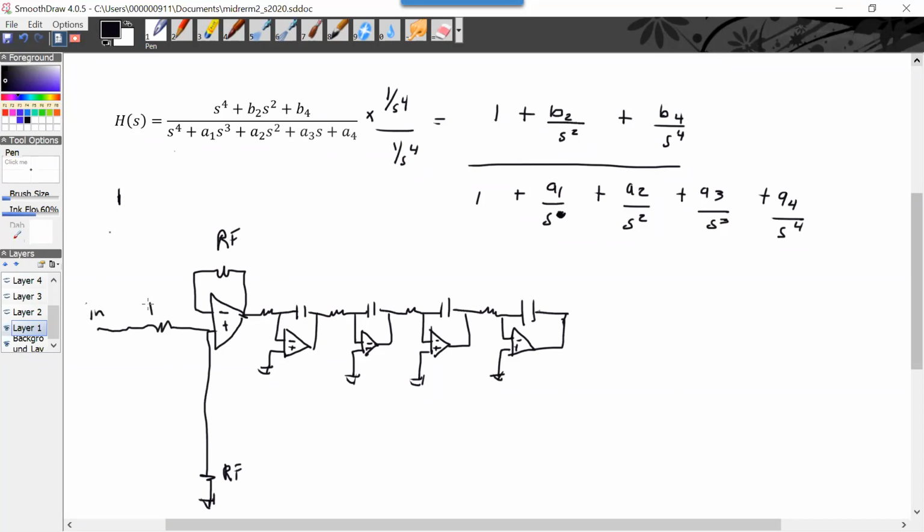This is in, and we'll call that Rn. Now, I'm just going to go over the answer. I'm not going to really derive it, okay? But here's integrator 1, and that constant A1 is set by R1C2. And it's negative, right? And we want to keep it negative because this is all negative feedback.